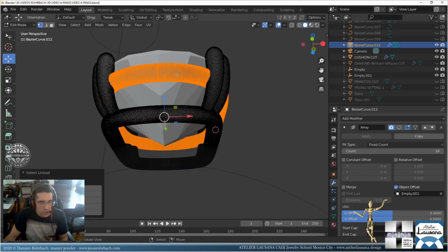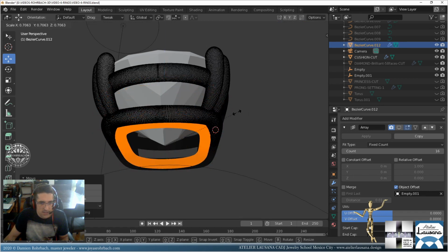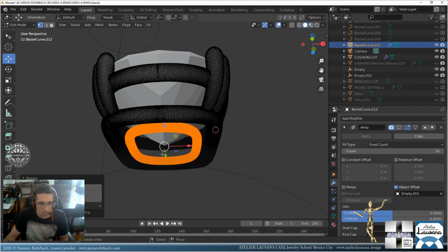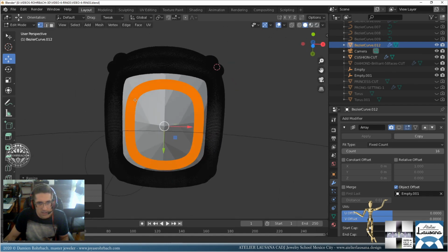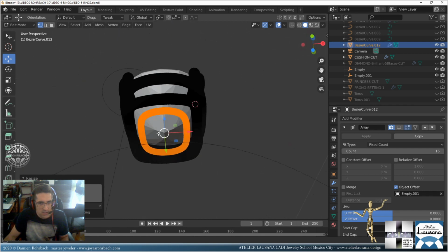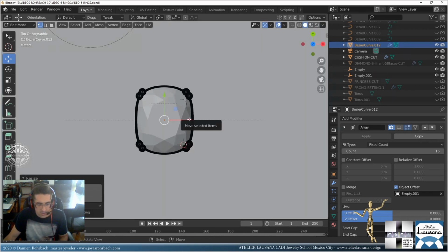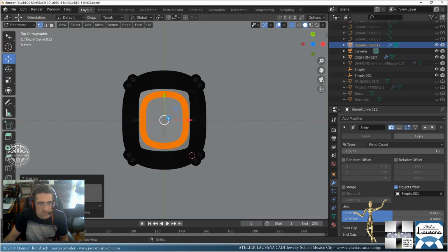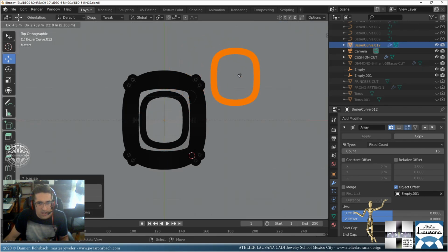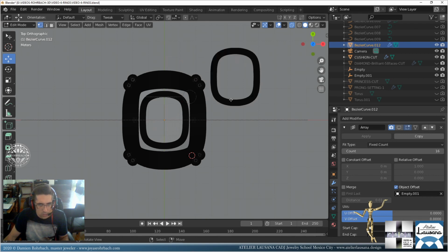Let's do an L selection, a Shift D. Let's move it down and scale it. I'm going to make a double bottom like this. Yeah, that's pretty nice. Now I just need a section of this. Let's do transparency, Shift D, and let's make very rough cuts with the B key, selection and selection and selection.